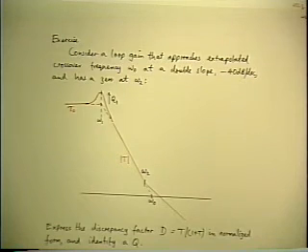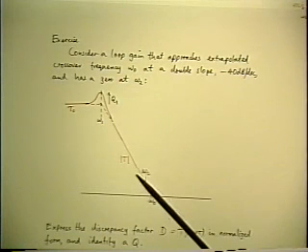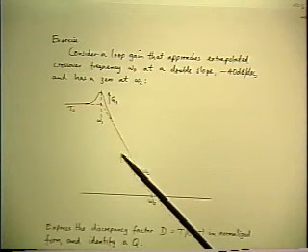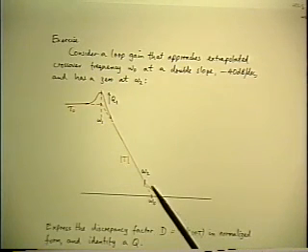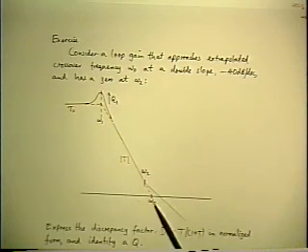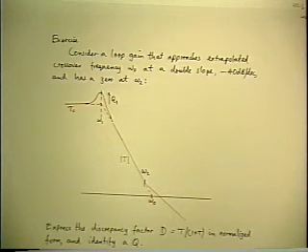So what you have to do is to put a zero in. In fact, I already mentioned this in the progression of how you design a loop gain in order to fill in that window appropriately. So since we already have two poles, you have to put one zero in order to sort of flare out the response and bring the phase lag back down before you get to crossover. So there's an analogous problem now. Where do you put the zero in order to get an acceptable closed loop response for your switching regulator?